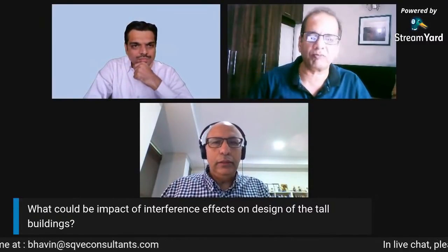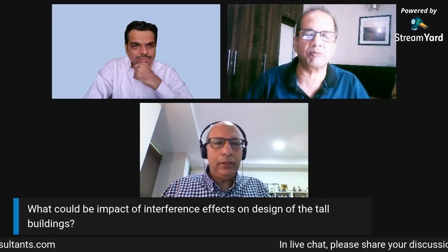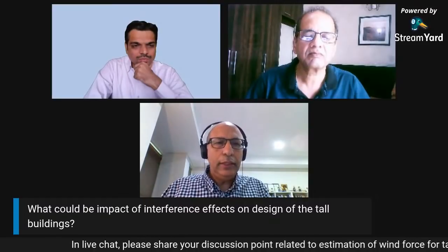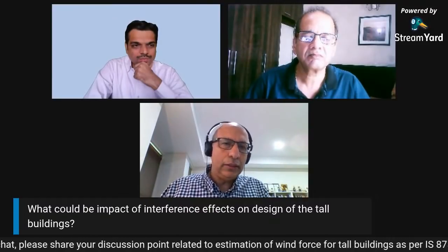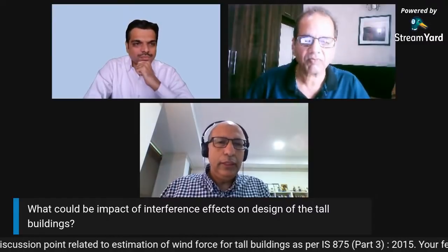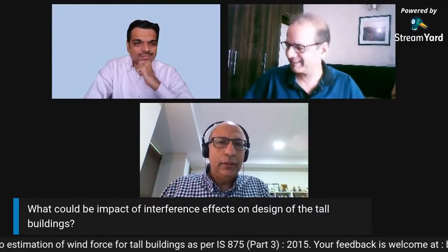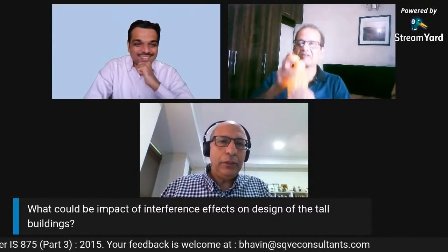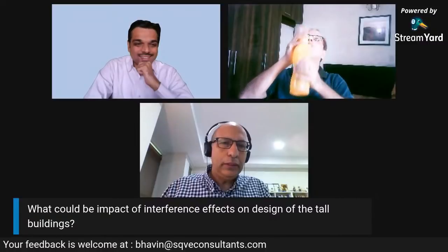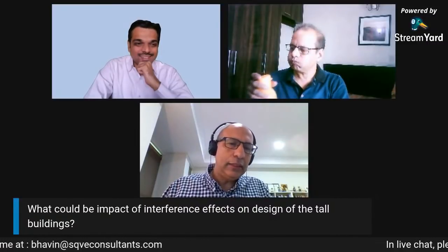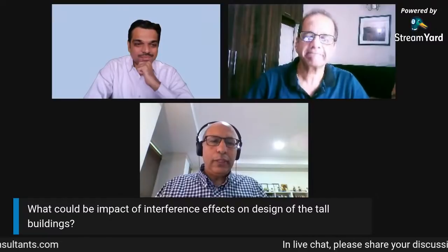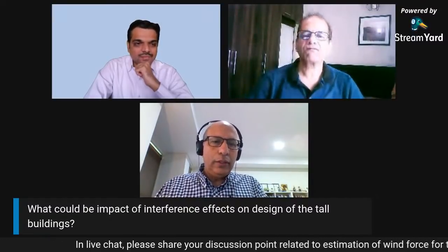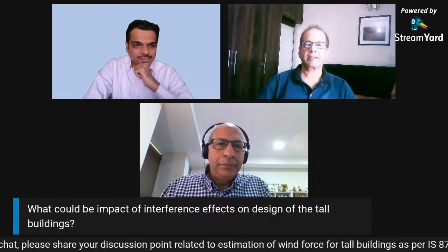In the case of short upper body orientation, suppose the building is three to one, but in the vast majority of cases, the impacted building is the downstream building. Now, obviously, depending on the wind direction, either building could be the downstream building. But the important thing to remember is the upstream turbulence. If it's low turbulence, the building on the side of the sea, for example, is going to cause more impact than the building on the side of the built-up city area.